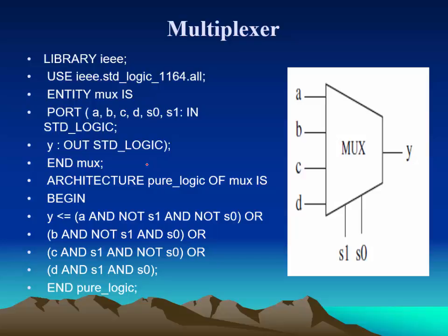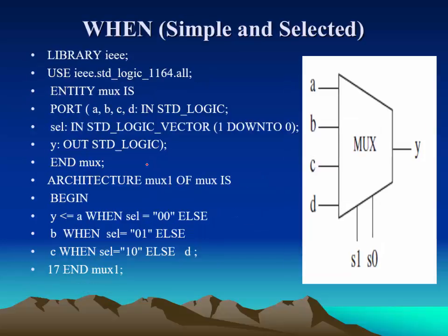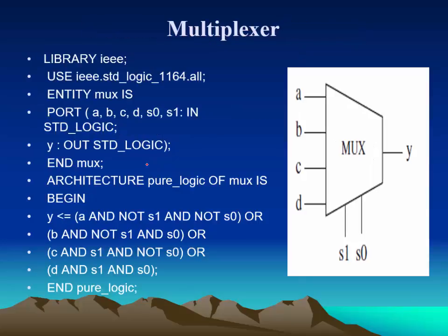Here's an example of a mux. This is a poor example of a mux. This is a better example of a mux, where we write all the logic functions. That's the way we would do a mux if we were to draw the schematic. Again, I downloaded these slides, and for some reason they're bulleted instead of the right format, but this is library IEEE, use IEEE standard logic 1164 all. This is the entity for the mux.